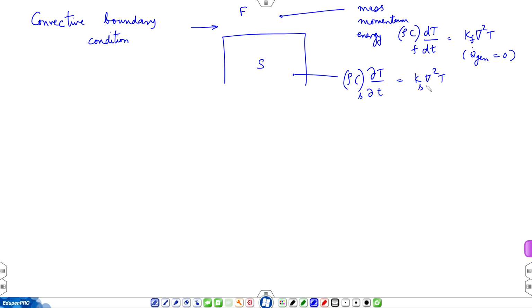Now, this is very much like the two fluid problem we had studied, and then there was an interface. We had the momentum equation in one fluid, momentum equation again in the second fluid. Here we have applied energy equation in one medium, energy equation again in the other medium. You can have solid and solid, solid and fluid and fluid, all possibilities are there. And then you have a demarcating interface. So, you solve these equations individually and then you have to blend them at the interface. So, there are interface conditions. What are the interface conditions?